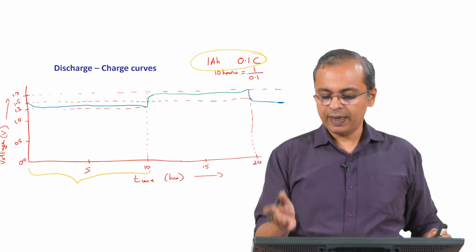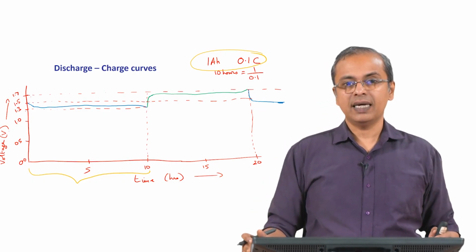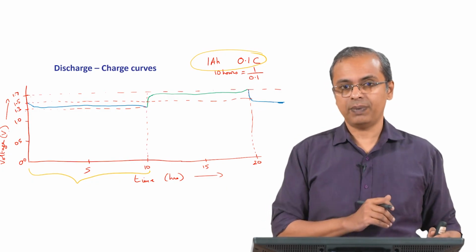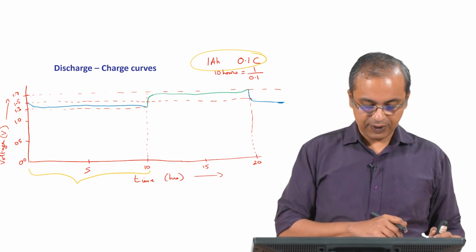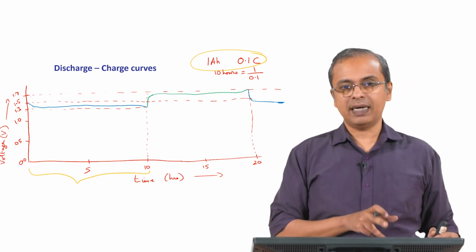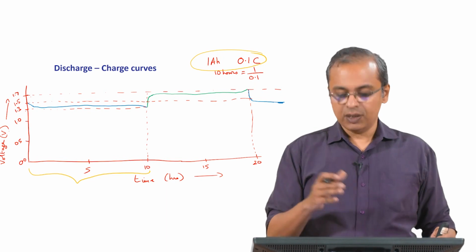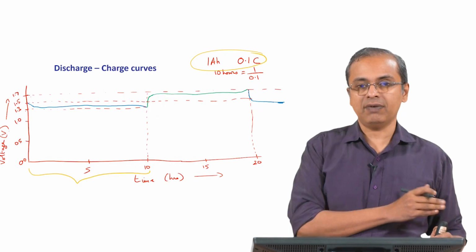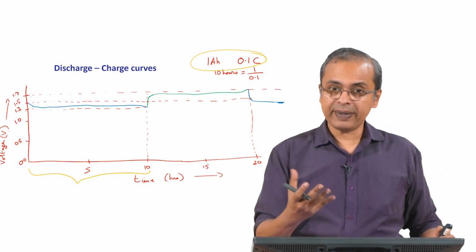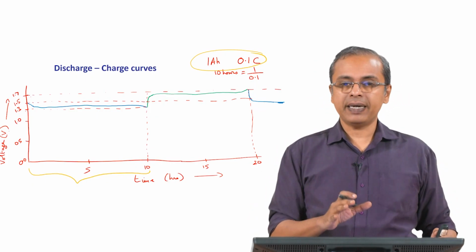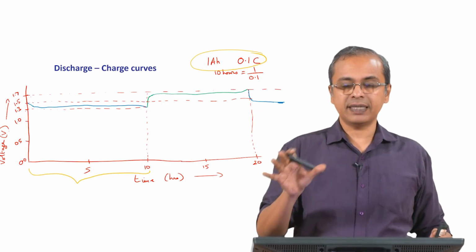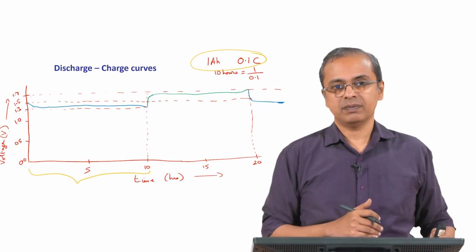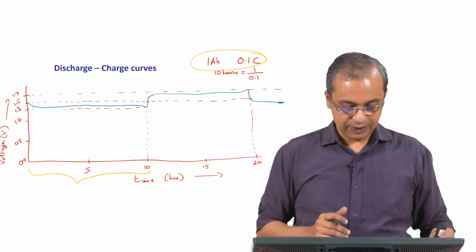So if, instead of 0.1 C, I use 0.2 C, that means I am doubling the current, so the battery will last only half as long in terms of time. Automatically that means the test will end in 5 hours even if everything were ideal. By simply going from 0.1 C to 0.2 C to 0.3 C etc., you will keep on changing the time anyway, but the original capacity of the battery is the same. Therefore, it may make sense to plot multiple different C rates with respect to the capacity, so that you can see if there is a difference in behavior because of the C rate.